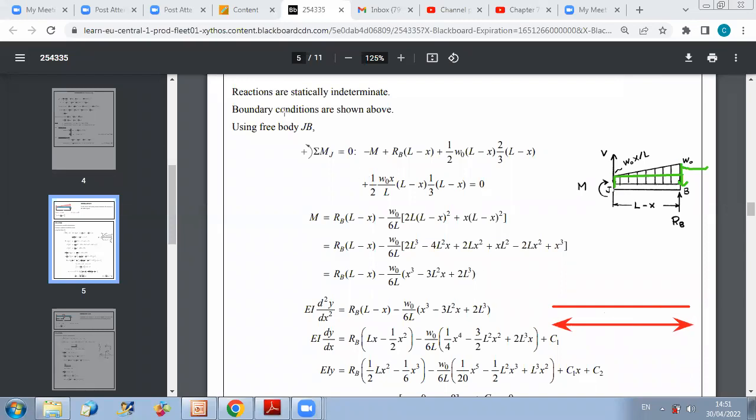For the rectangular load, I can replace it by a force at the center. So here, this is the rectangular load. And the value of it is L minus x times omega x. So it's L minus x times omega x, and omega x is omega 0 times x over L. So this will give me the rectangular force, and it's at a distance from the cut.